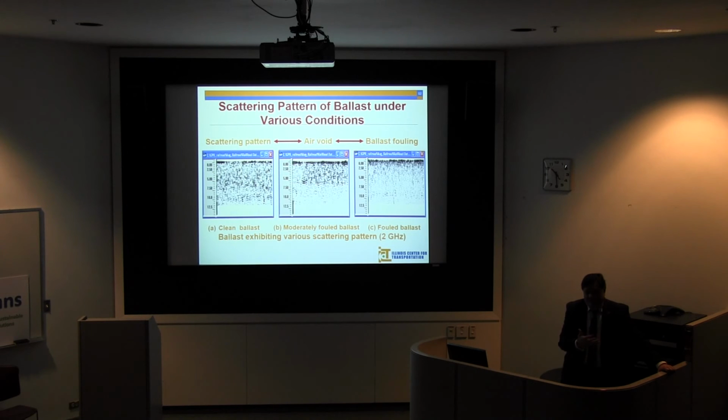And that's what got me excited about GPR. So what I did, I was at that time at Penn State, and they have a test track, so I went there and made cores, and I made voids of, at that time, 1.5 to 2 inches, and filled some with water and put this concrete back and so on.